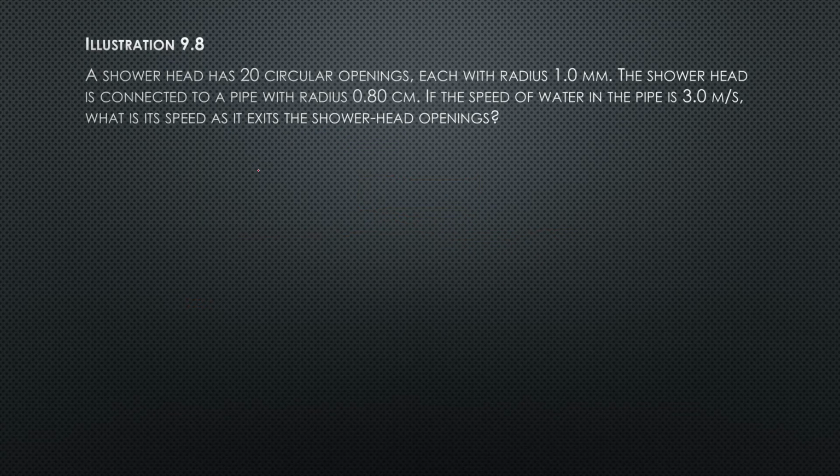So let's say this example, a shower head. A shower head has 20 circular openings, each with a radius of 1 millimeter. The shower head is connected to a pipe with a radius of 0.80 centimeter. If the speed of the water in the pipe is 3 meters per second, what is the speed as it exits the shower head openings? Probably you have encountered a shower head, or some of you have this in your bathroom.